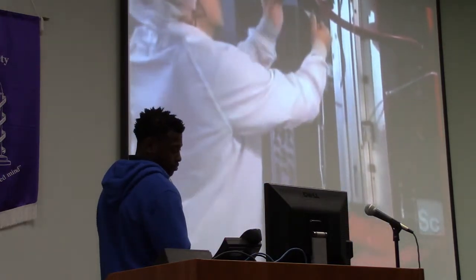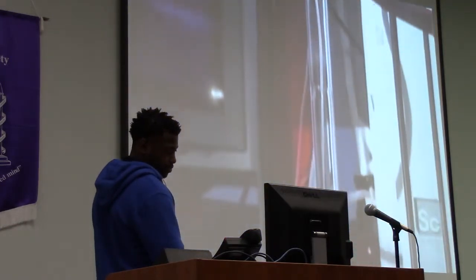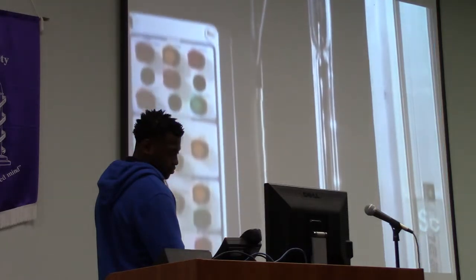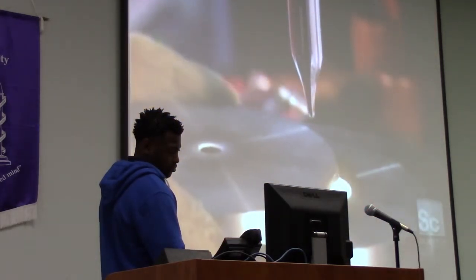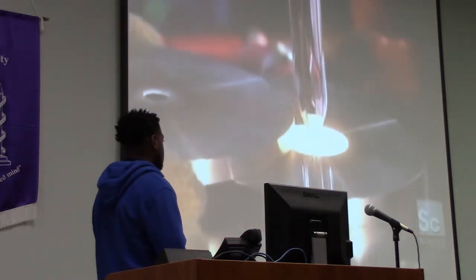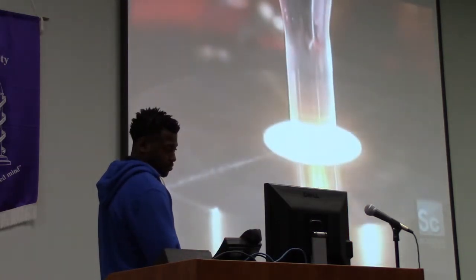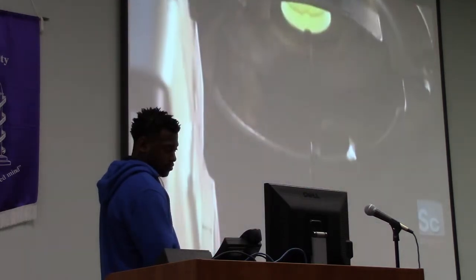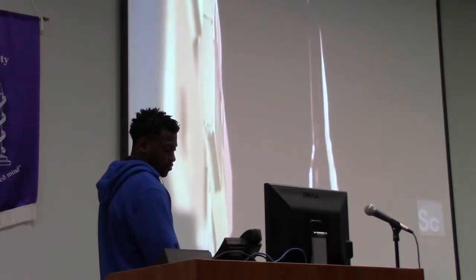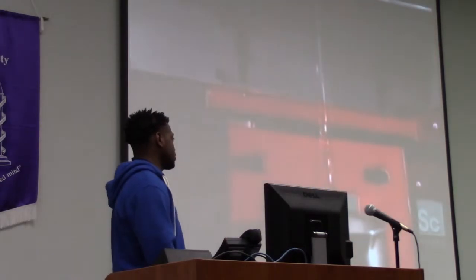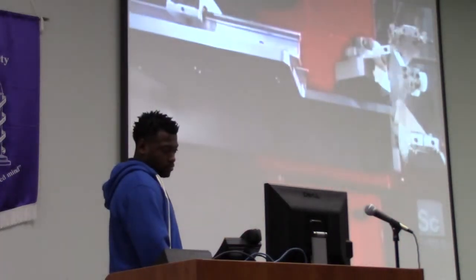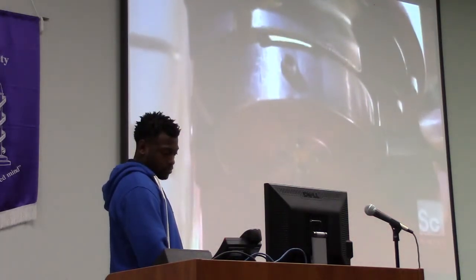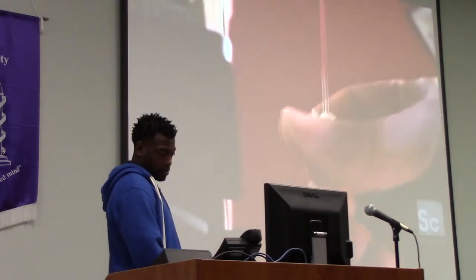Then they install it vertically into the drawing tower, which will draw out the final shape. The drawing tower's oven heats one end of the preform to 3,600 degrees. Gravity helps pull it down, like honey dripping from a spoon. Then, using a glob of glass as a weight, they stretch the soft glass and keep stretching it until they've formed a thin glass fiber.